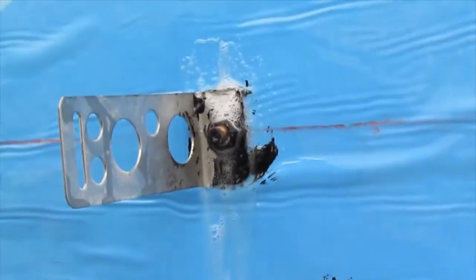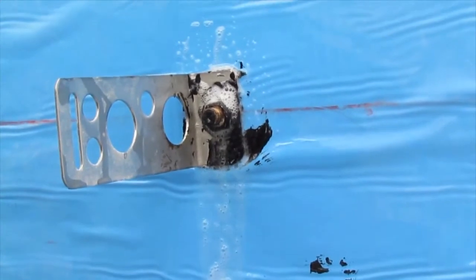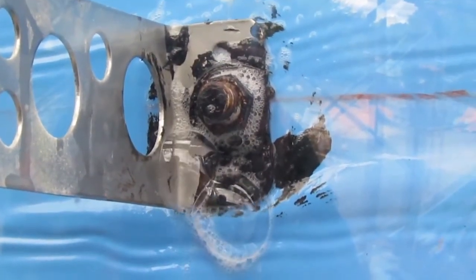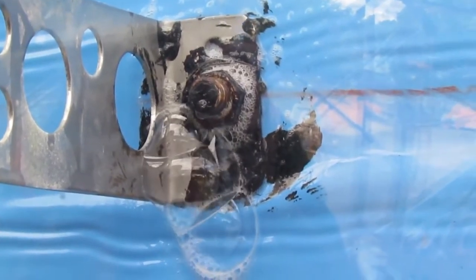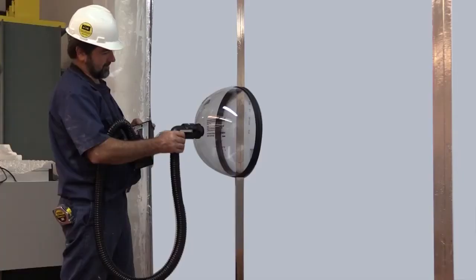In order to use the detector, a surfactant is first applied to the area being tested. A dome is placed over it and a pressure differential is created, drawing air through the leak or deficiency to show the bubbles form, as you see here. The primary areas of concern for air leakage are joints between the materials, penetrations through the materials, like fasteners or masonry ties, and junctions with other assemblies. In the case of paint, the paint film itself should also be tested.